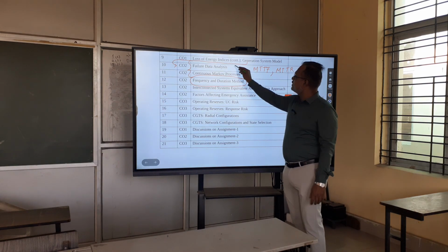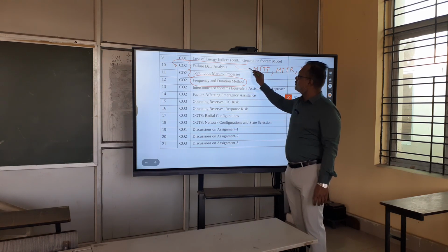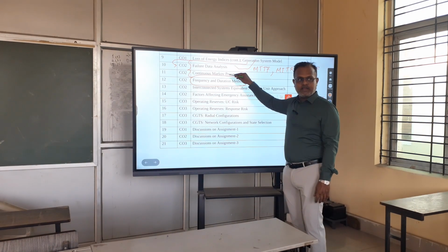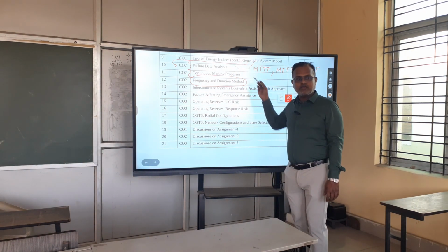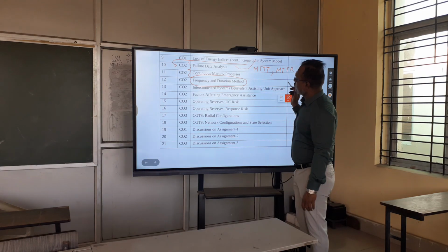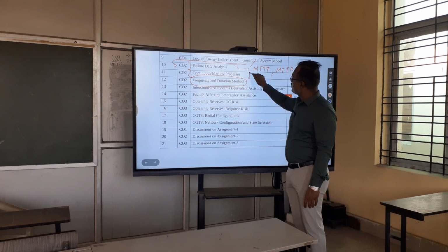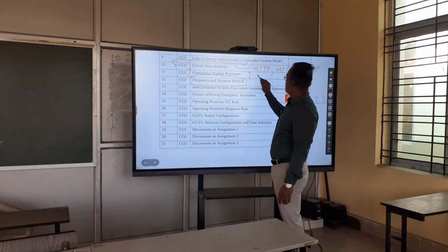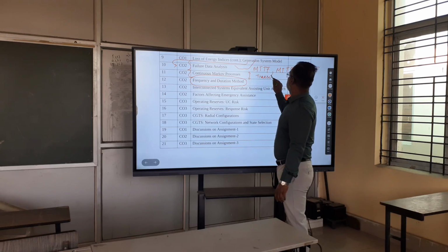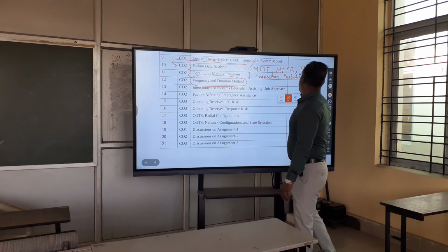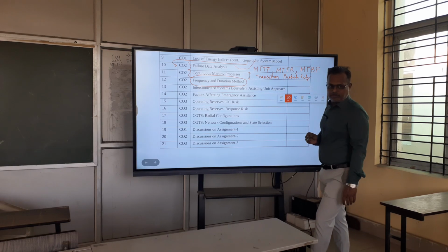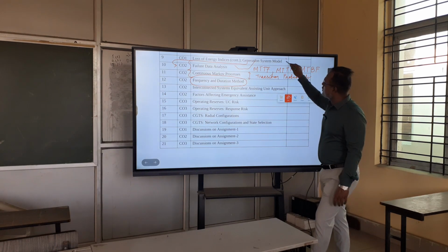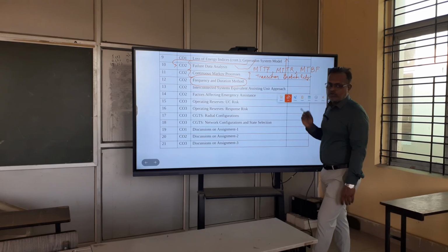And we discussed that a typical reliability curve, which is something like this: initial failures, later failures, in between only service failures, right? Then we discussed continuous Markov process, where we talked something about transition probability, or the state transition matrix. Okay. So this is all about the background for frequency duration method.